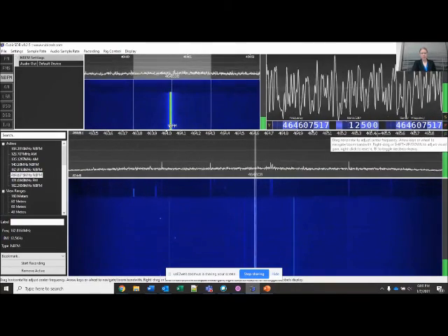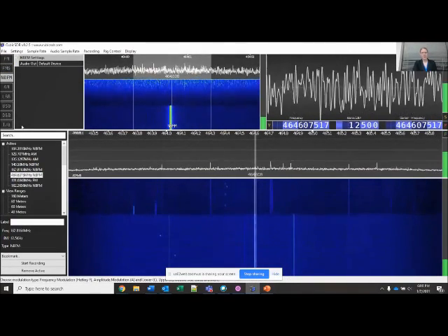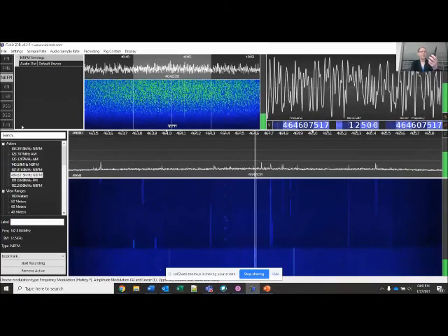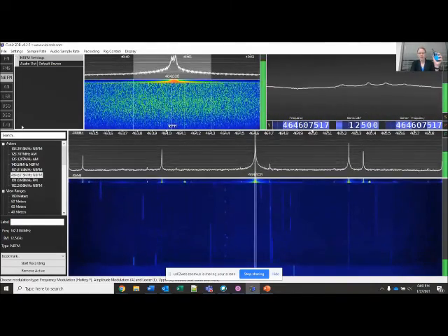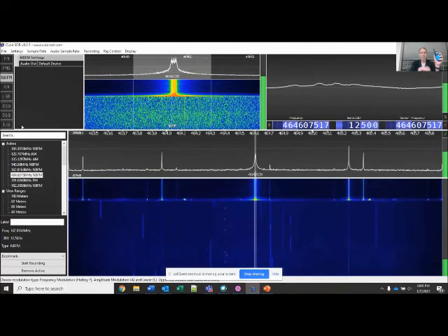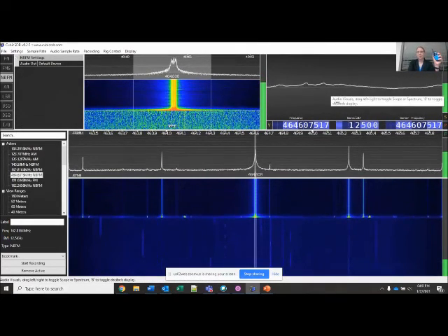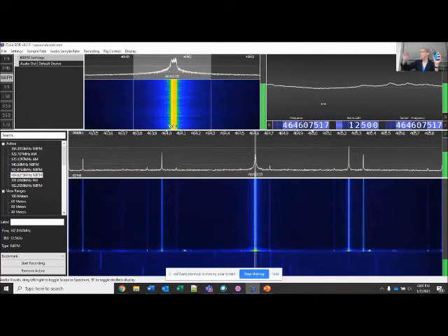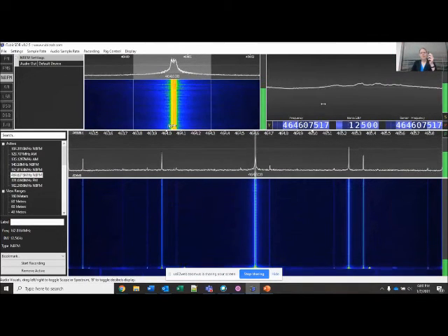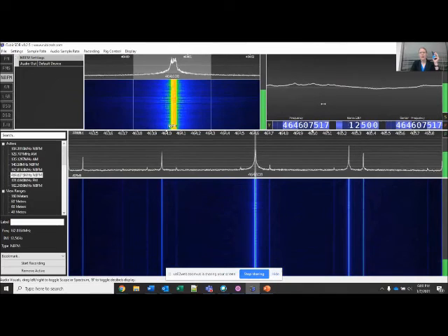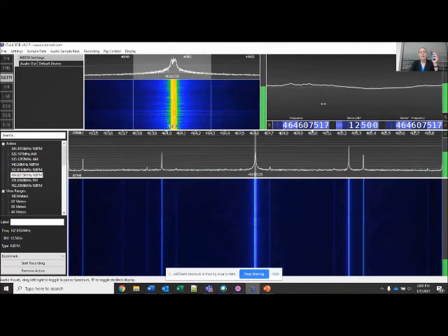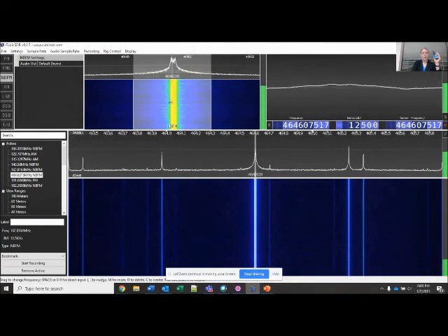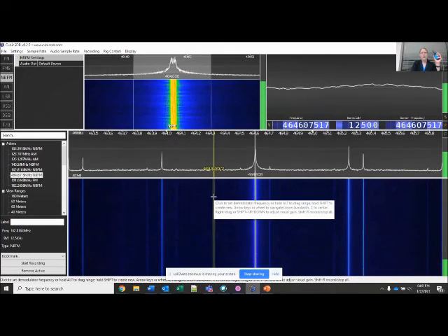So I'm going to stick on narrowband. And now I'm going to take that walkie-talkie that I totally stole from my children. And when I turn it on, a couple of really interesting things happen. So up here, I go from having nothing but static to having a relatively moderate signal. And it's not picking up my voice terribly well, I think because there's a bit of an antenna mismatch. But you can see it's settled down into a pretty nice signal over here. But look what happens when I turn it off.